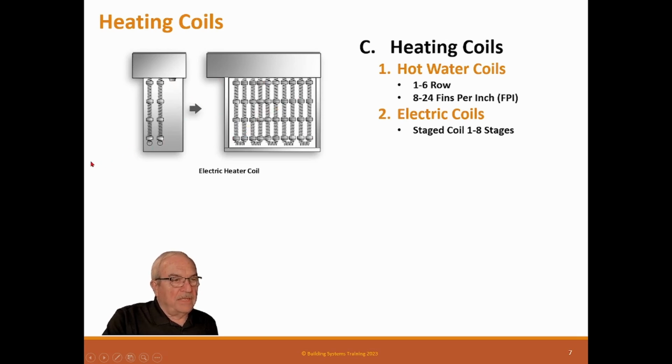So many times I've had to come in and build baffles in here to push more air across this coil or to certain areas of the coil because it was too hot of air. So that is one problem. 1 to 5 kW coils, that's just a practical limitation of the amount of power going into it. And that's one reason why we stage a coil. Stage it to keep the kW smaller in the coils. Or SCR, silicon control rectifier, which means it can be modulating control, it can be 0 to 100% or anywhere in between. Stage coils, of course, are off or on.